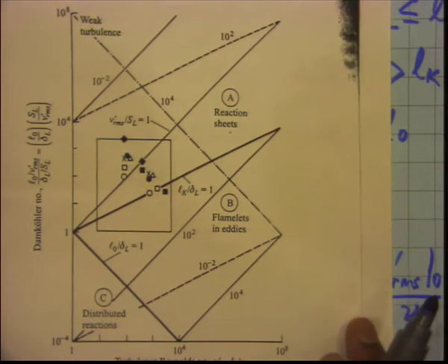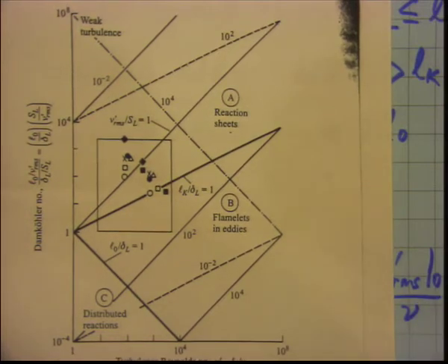Now, this is a plot which helps us understand the various regimes of turbulent premix combustion. There are various lines on the plot, and before we go to the lines, let us see what we have on the x axis and y axis. The x axis, I told you, is the turbulence Reynolds number, which is V prime RMS LO divided by nu.